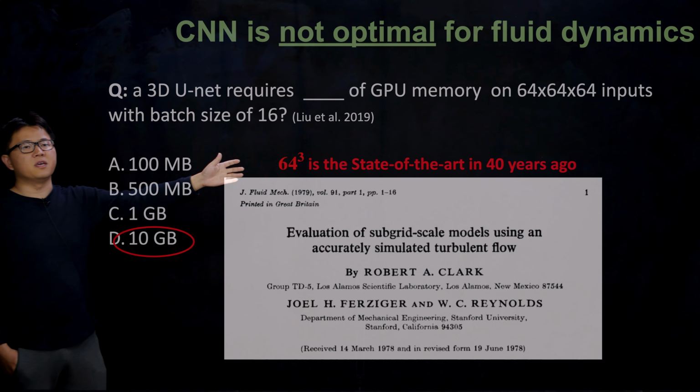Okay, so now I'm going to provide my solution to this. It's a framework called neural implicit flow. Neural implicit flow consists of two networks. The first one is ShapeNet. ShapeNet takes spatial inputs x, y, z and outputs the quantity at that location. The other net is called the parameter net. The parameter net takes external factors other than spatial ones. Anything else is put in here, like time, parameters like Reynolds number, and sensor values. You put them in the parameter net.